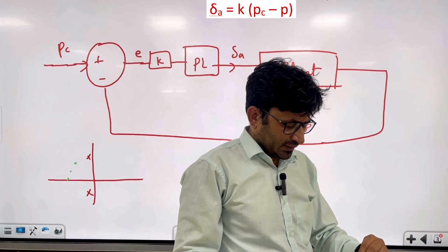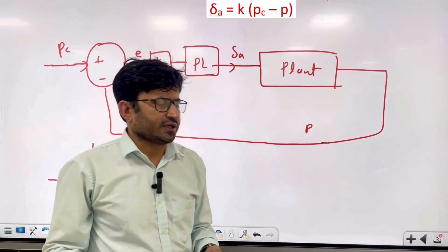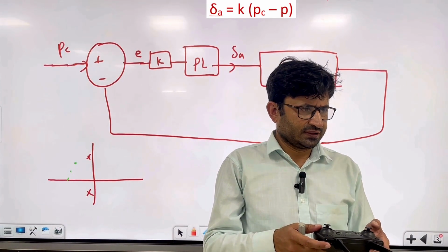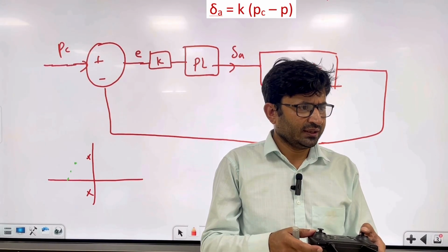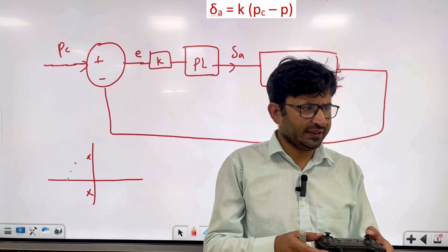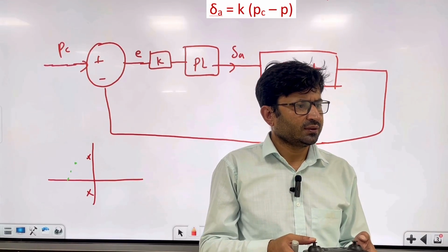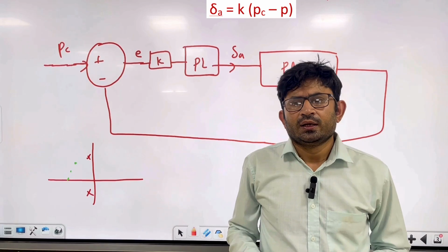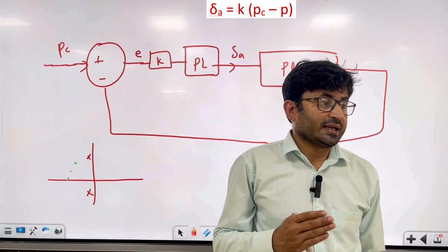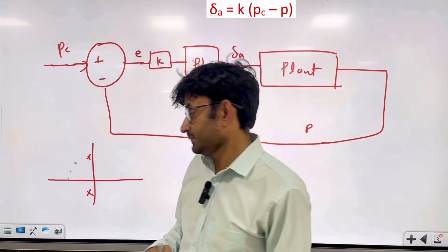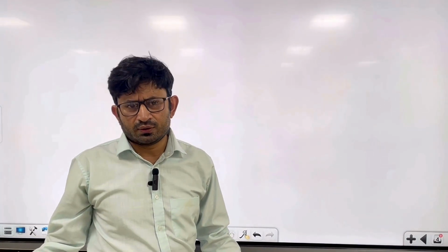So let's consider the very first case, a very simple one. In manual flight mode you give the stick command. For example, let's say I have a stick with me, so this I can configure as pitch down, pitch up, roll left, roll right, rudder left and right, and this is the throttle, which you can configure. Now when you give the stick command, it can directly convert into angles and supply to the plant. For example, consider the same roll rate example.